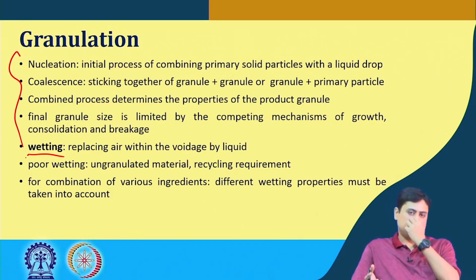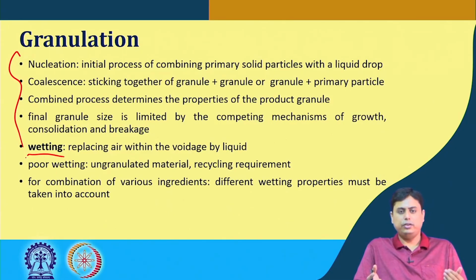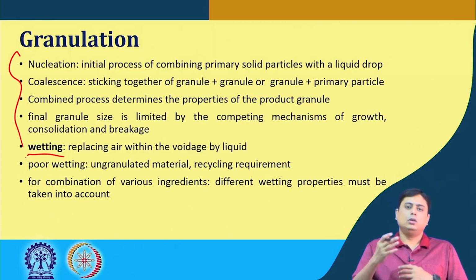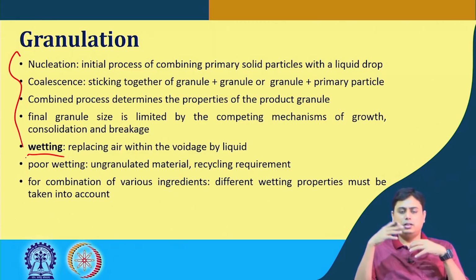Now, the granule size is basically limited by the competing mechanism of all these three rate steps that we have seen, that is the wetting and nucleation, then consolidation and coalescence, and it is followed by attrition and breakage. So the interplay of all these three phenomena dictates the final granule size.